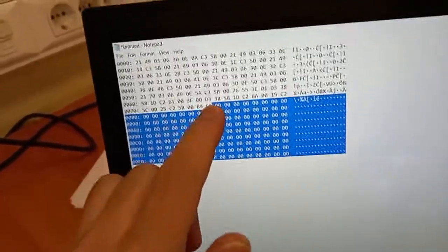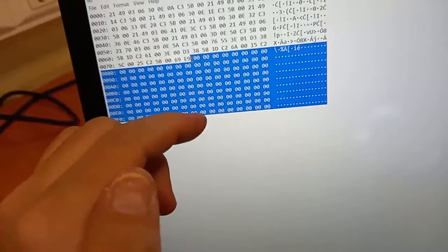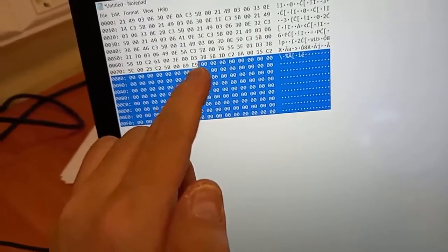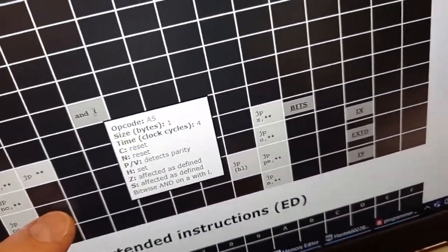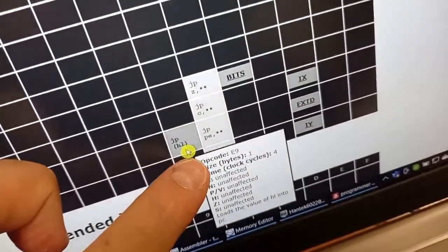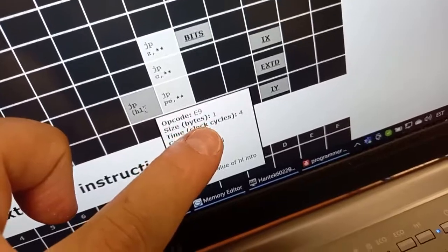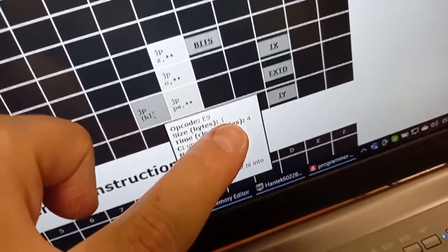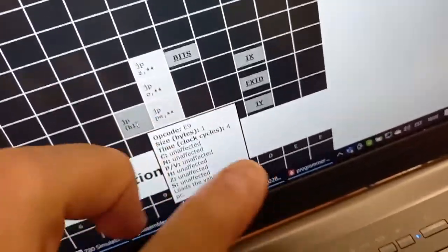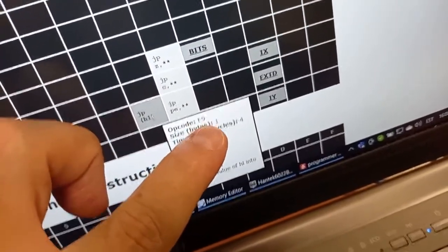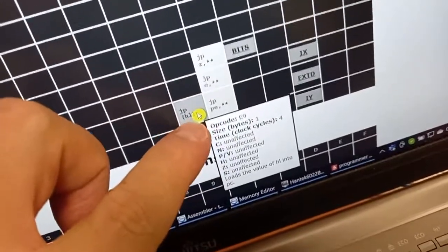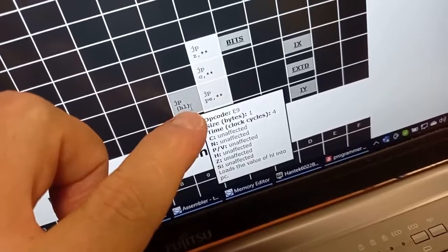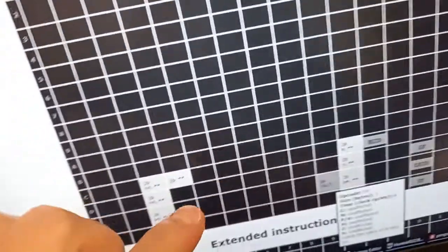And the last jump doesn't jump to some number, it jumps to HL. This instruction has just one byte. For example, here you see different jumps, and one of them is HL. The size of this instruction is 1 byte, because it doesn't need 2 more bytes explicitly set where to jump. It knows where to jump. That means E9 means jump to HL, and before that we have put into HL H is 0 and L is C. That's the reference to the next node.